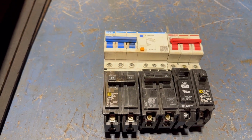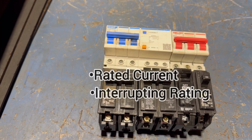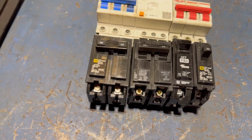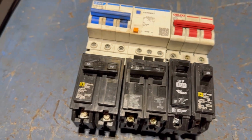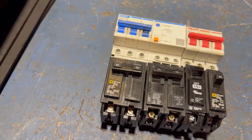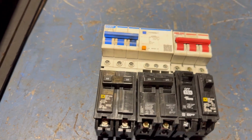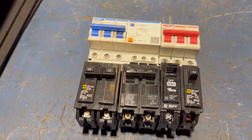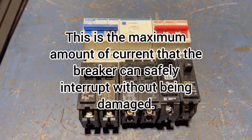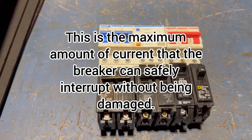One of the first things we want to talk about as it relates to the rating of a breaker is the rated current and the interrupting rating, right? First I'll be going through the interrupting rating. This is the maximum amount of current that the breaker can safely interrupt without being damaged.